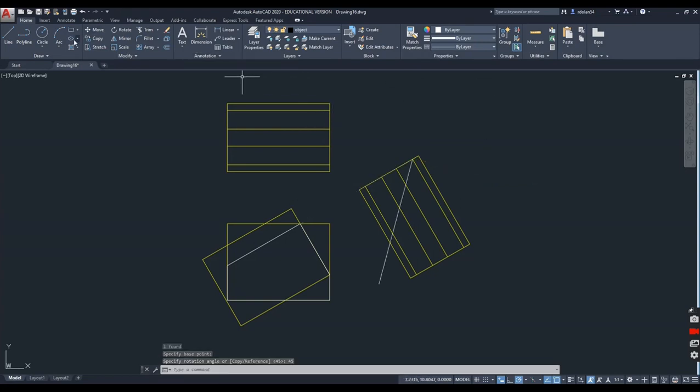I'm going to do the same thing again. I'm going to draw a line from that same point to this second line here. Click there. I'm going to highlight it, right click, go to rotate again, pick that endpoint, and pick 135 degrees. Now I'm going to trim those two up from there to there. So that is going to be my V.